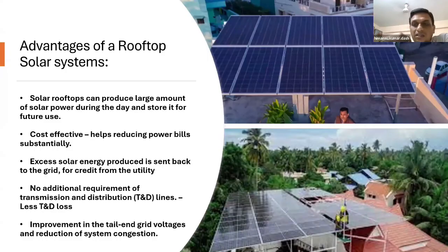Now, for the domestic customers, the situation becomes much more challenging, because we know that the growth of buildings, the growth of human assets that consume electrical energy, is growing day by day. So suppose the utility has installed a 1 MVA transformer, and there are say around 500 households in that zone. Now 5 years ahead, suppose that 500 households expands to 2000 households. So what will happen to the 1 MVA transformer and the utility network that the utility company has installed? So this has to be augmented definitely.